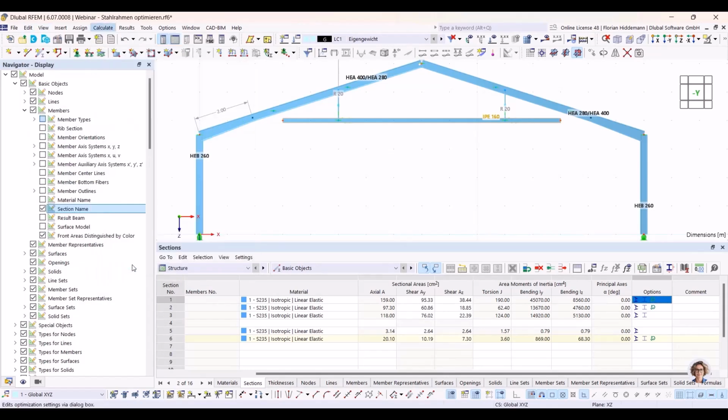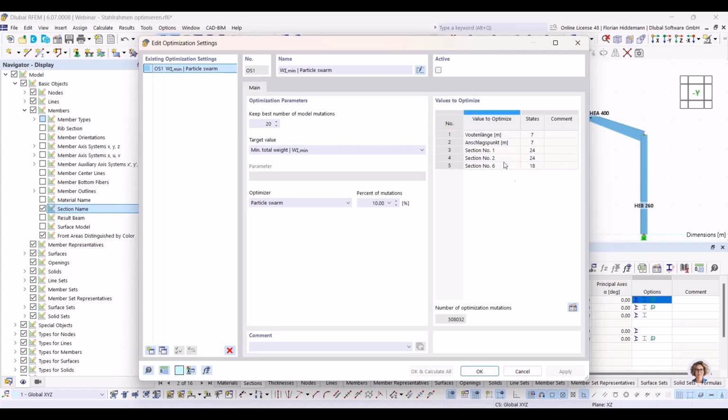And we go back to the settings here. And now you can see this is from the challenges from the PowerPoint presentation I showed before. These 3 sections here will sum up to over 500,000 possible combinations. Because of this, we are using sections as a discrete parameter, where there are no values in between 2 alternatives. The ant colony is the approach you want to choose for this, because this algorithm is very strong to find the best solution for those problems.